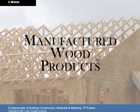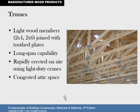All right, and now on to manufactured wood products. So different structural members essentially. Trusses, especially as our next chapters will be on residential or low-rise framing, play a very big, important role today. They are typically made up of 2x4s or 2x6s, and then they have toothed plates or gusset plates. That's what's pictured right here. The whole truss is laid out on a jig, and then the gusset plates are placed where they're supposed to be, and hydraulic presses quickly put them together.